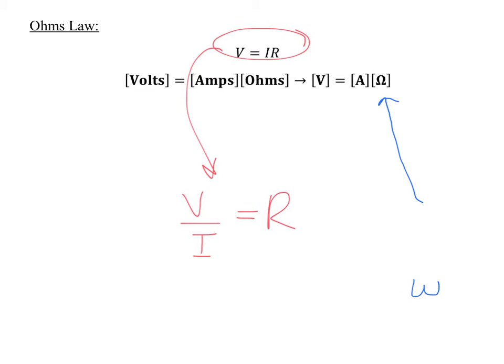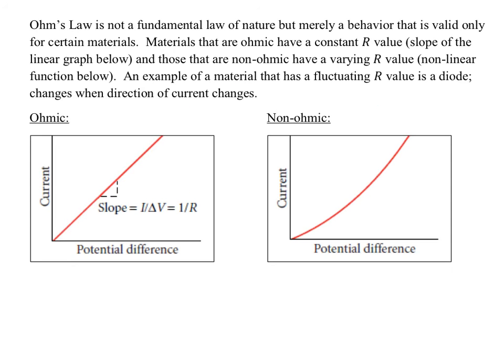All right. With that said, let's take a look at what we're talking about, which is non-ohmic. If you increase the value of, say, the current or the voltage, the resistance of an item should change accordingly if it follows Ohm's law. So if I look at Ohm's law, V equals IR, and say I doubled the resistance and kept the current the same, I should get double the voltage out. Because I double R, I double V. That's Ohm's law. Well, some materials are ohmic, others are not. And the graph you're seeing is indicating the slope of this. So let's take a look.